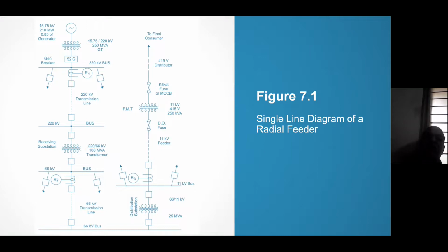Instead of 220 kV, I might have to transmit at 400 kV also. Here I have taken 220 kV as one assumption. Here 220 kV is economical, but it can be 400 kV also and 765 kV also. But anyway, 220 kV was economical there, but now my distance of transmission is hardly 50 kilometers, and 10 lines have gone, so out of that one line power has also reduced. So now my economical voltage is 66 kV.